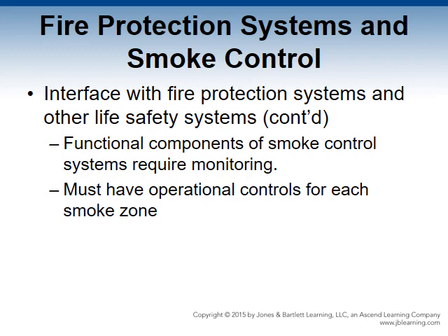Some codes allow motorized damper installations and fixed ventilation openings at the top of the elevator hoistway. Smoke detectors mounted at the top of the hoistway can open the dampers. The dampers improve pressurization and mitigation of the winter stack effect.